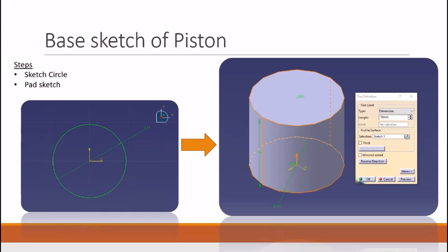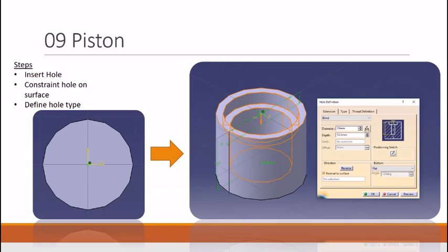The next step will be creating the base definition. For this purpose I chose the circle, although there's another way of doing this, which would have been creating a shadow command with all the other parts already included. But we're going to start with the base. The next step, after padding that base, would be to create your countersink hole. The definitions of the hole itself can be found in your engineering drawing, and you can simply apply that definition in your hole command once your hole is already constrained.